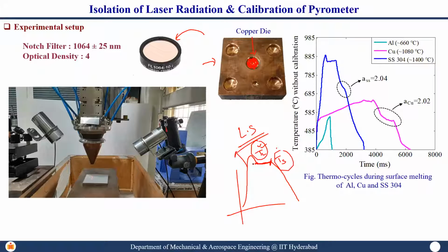The other way is you heat that material and take your pyrometer there and set emissivity at different values. Let us say I'm keeping a thermocouple over here, measuring its temperature. And parallelly I focus my sensor over here, measuring its temperature. Here I am supposed to set the emissivity value, so I will keep on changing my emissivity value. The next step is calculating the emissivity. Once the calibration is done, you need to calculate the emissivity. Now how do you do the emissivity calculation?